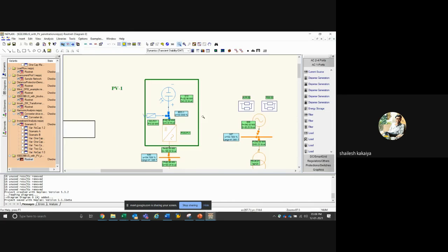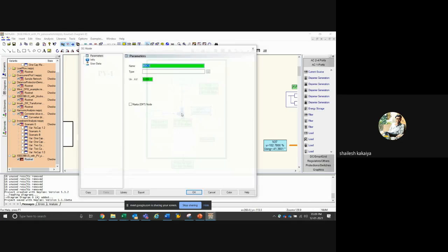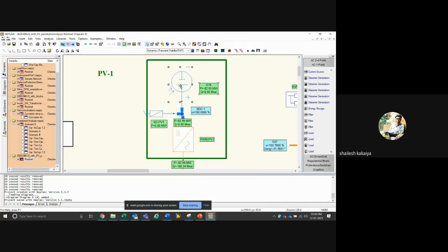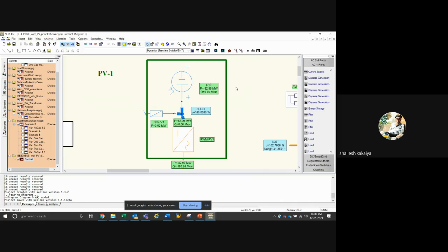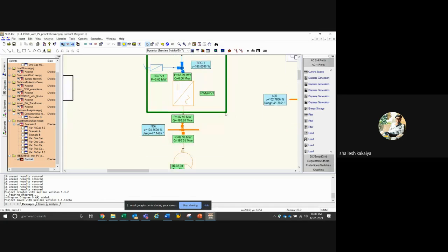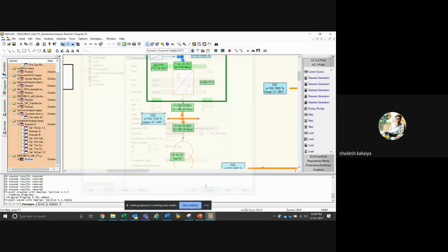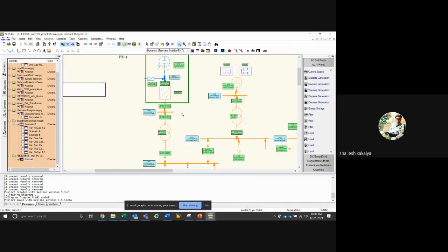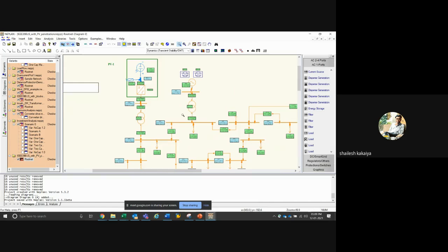So there are some blocks in NEPLAN which can handle DC as well as AC. You can see here this particular system is a DC node, the DC node with the solar generation, the set voltage generator here. And there is a PWM converter model with the relevant power flow parameters again, and then you have an AC bus. You can see this is a node which is an AC bus. So we can combine both the DC systems and AC systems, and the relevant converter models have been built into NEPLAN.